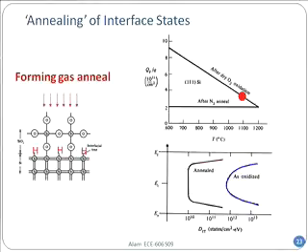So this is saying that in the mid-gap region, remember the mid-gap regions are the ones that are most interesting. We're talking about traps, right? Do you remember Shockley-Read-Hall, that if you have a lot of traps close to the conduction and valence band, it doesn't matter. The ones that are most effective for Shockley-Read-Hall recombination or surface recombination are the ones in the mid-gap region.